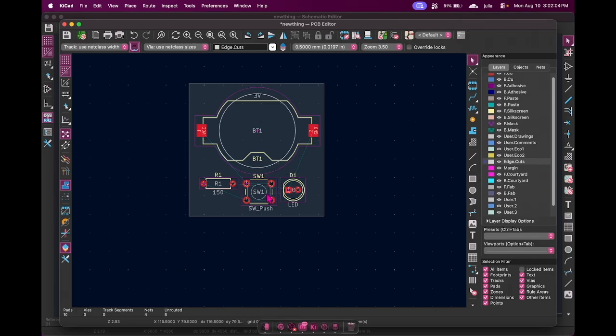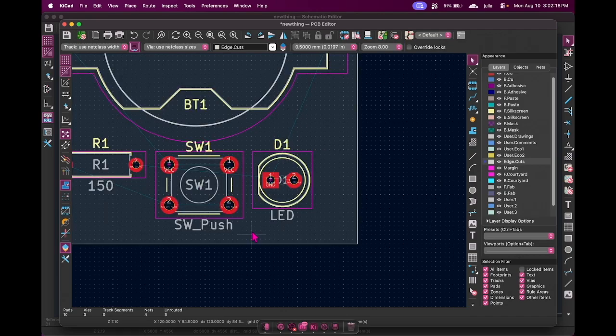I'm so sorry. Yeah, but trying to select from the top left, as you can see, doesn't select the whole thing. It selects a part of it, and it's weird. I could not tell you why KiCad doesn't let you select from any corner. It has to be the bottom right corner.